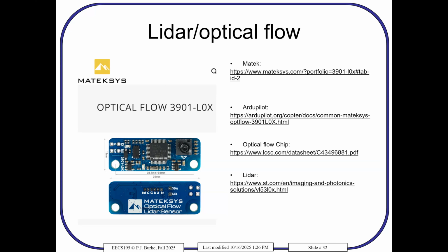So it's an autonomous vehicle, and on the top of it has a LiDAR that points the laser around and creates a three-dimensional map of the world, and then you get in it and it drives you to where you want to go. So that is a method of using LiDAR. However, it's a very, very big LiDAR system. It's the size of a desktop computer or bigger. So it's not drone available yet, at least not for our small drones. But on bigger vehicles, you can use LiDAR to create a three-dimensional map of the world. You still have a range issue. So you have to have pretty powerful lasers to get 10 meters out. But it is in use in Waymo self-driving taxis.